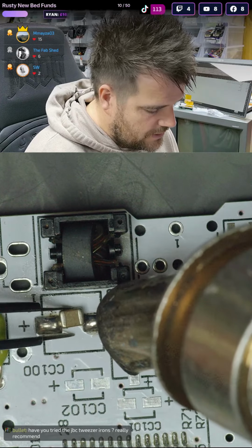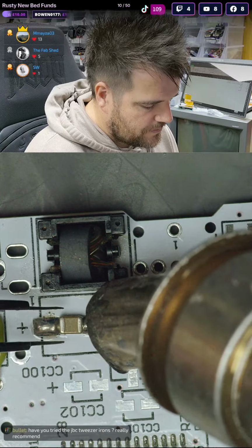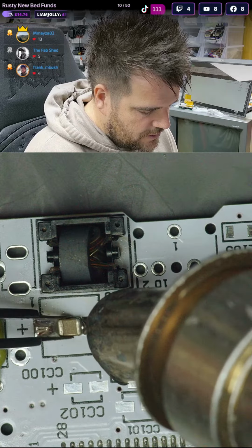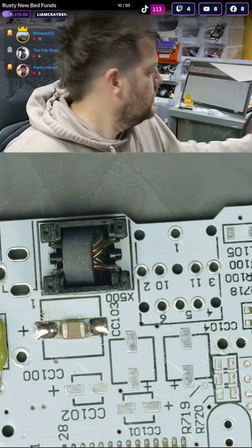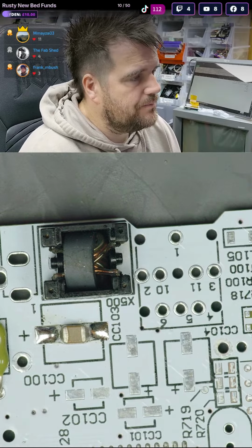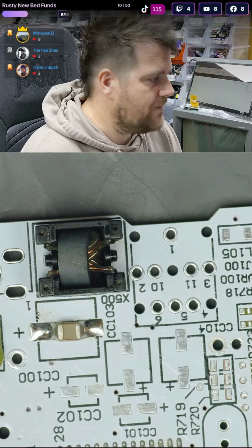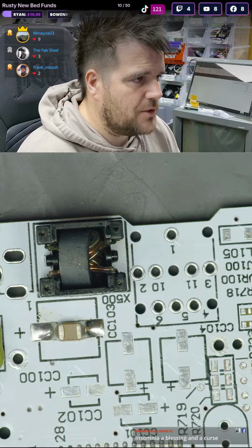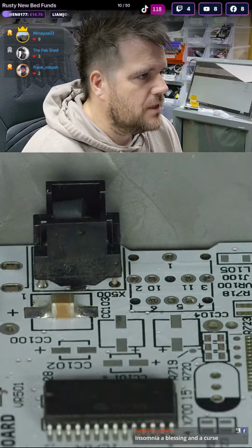Tweezer irons, yeah, I used to have them at the start. It's one of them things where I think you feel it's beneficial and it'll make jobs easier. Like I think at the start when you're trying to learn the soldering, you look for tools to help your job, but personally I don't think it's worth the desk space and the time to switch between irons. If I had a nice setup and a proper JBC with the dual setup that's nice and quick, I'd probably use them just for whipping off caps and things, but that looks quite nice.